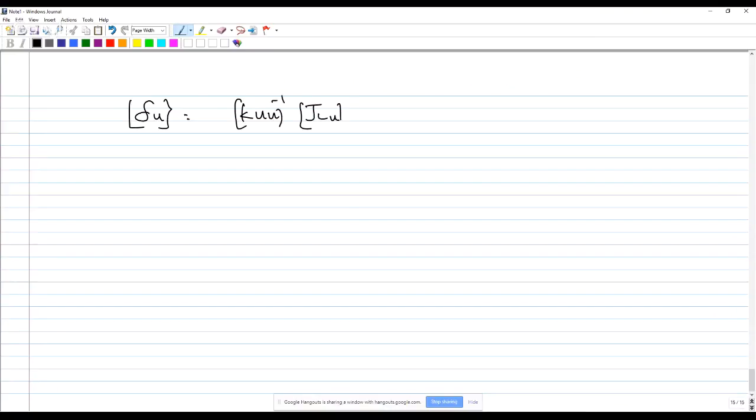The U stands for unrestrained degrees of freedom. So we can get this from the solution using a program. Once I get this, I can find the end moments for the ith member as k of the ith member into delta of the ith member plus fixed end moments of the ith member.